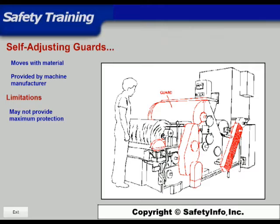Self-adjusting guards are the preferred type when machinery danger areas must accommodate varying size work materials because they provide a barrier which moves according to the size of the stock entering the danger area. Advantages of self-adjusting guards are that they are often available from equipment manufacturers or are commercially available. The limitations include not always providing maximum protection, possible interference with visibility, and may require frequent maintenance and adjustment.